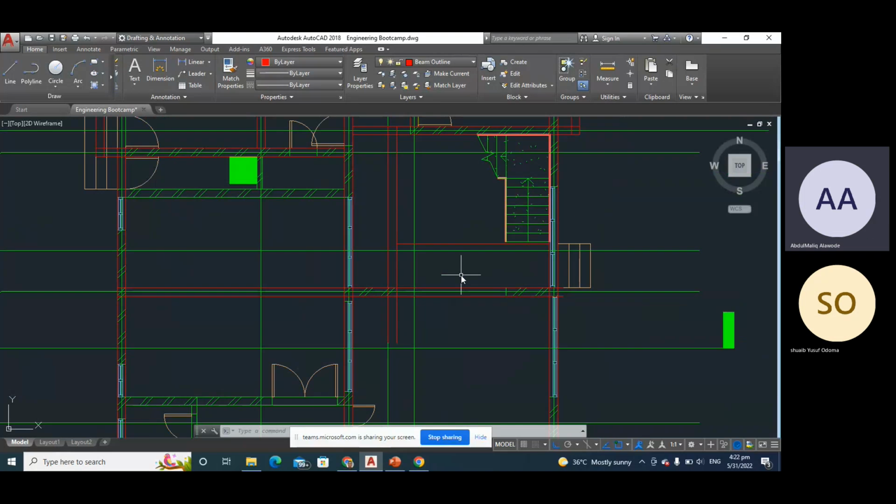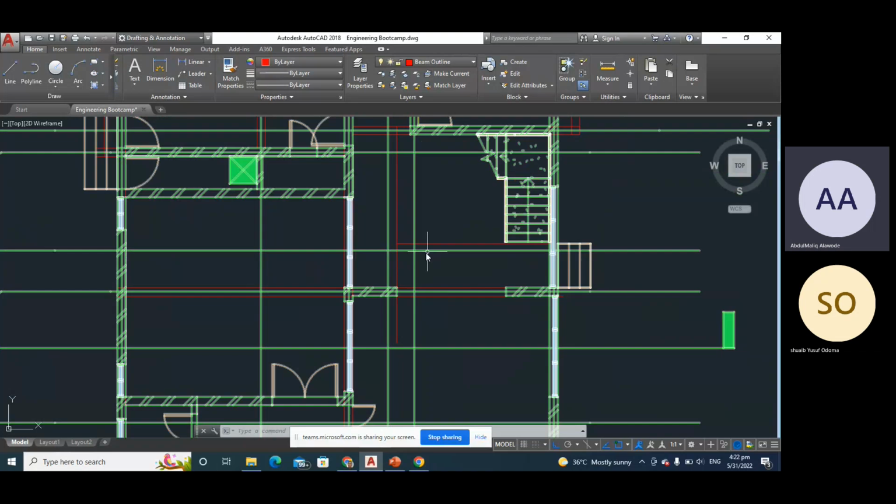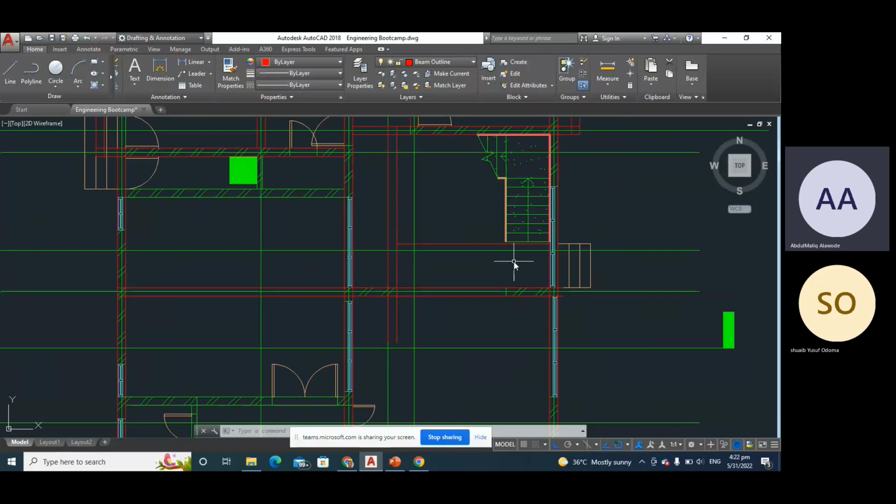Now my question is, if I'm on the first floor, this slab, is it cantilever or is it not cantilever? I said it's cantilever. Why? I said it's not cantilever. Why? Now it depends. When you are designing, I can decide to span my slab anywhere I like. What I mean by spanning is I can decide how the load distribution of the slab is going to go. Now, the normal convention is if I take a section YY, if I cut this slab like this and I check it like this, what I'm going to see is going to be a cantilever.